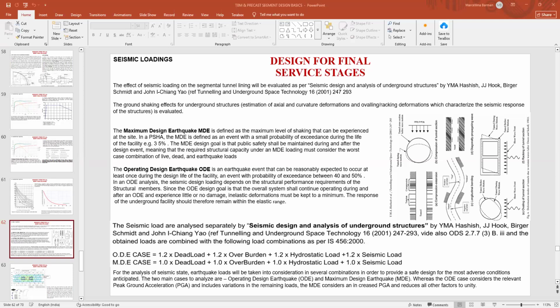No, I'm asking that in any type of structural design, you are always putting additional factors. In Eurocodes, we are putting partial factor of safety. In IS code, we have partial factor of safety. In any code you see, we are putting a partial factor of safety. Sometimes it is 1.5, 1.3. Why are you putting partial factor of safety? To take into account the uncertainty of predicting the load accurately.